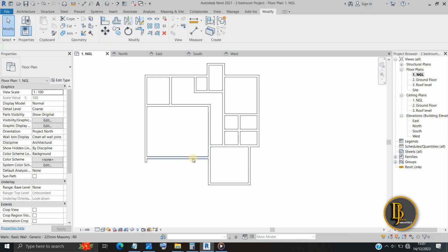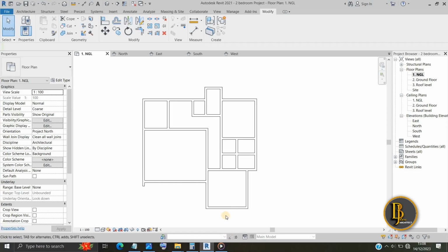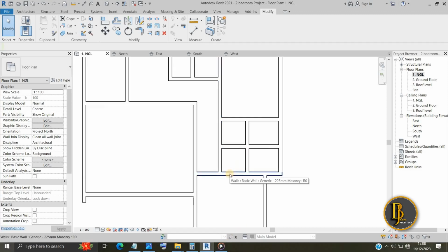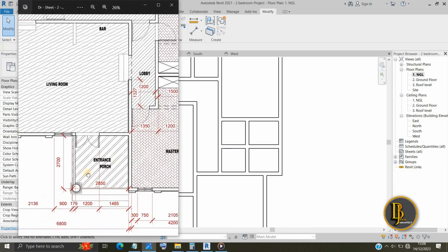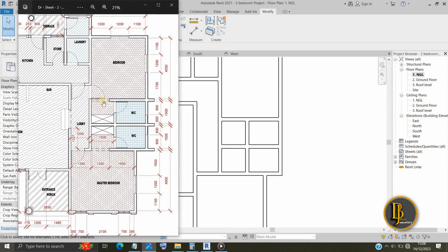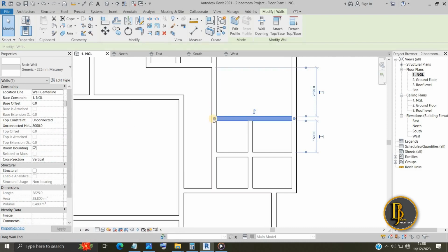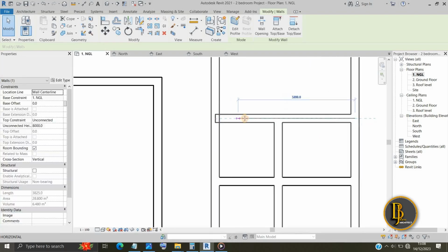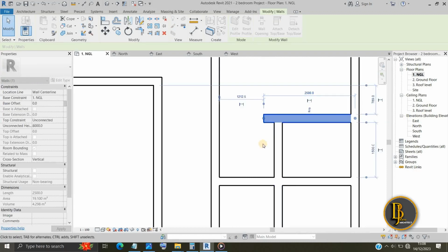So now let's create some floors. Let's go. Before we create floors, if you notice, our plan has a walk-in closet here. There's a gap here, and a gap here. We want this space to be our walk-in closet. So let's detach this wall and make it stop here. You click here, you see this blue icon, drag it, and stop somewhere here. Doesn't matter, let's stop it somewhere.